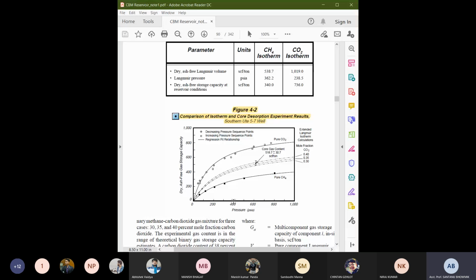Now if you have seen this, you have also seen that in the mixture, as the higher adsorbed gas percentage is increased, the adsorption rate capacity is also going to increase. Okay, so this is true. Again, you have also seen from this graph how the shape of the graph at initial stages is going to vary, is going to be dictated by the isotherm. And again, how the ratio of different gases can be analyzed from a single graph.